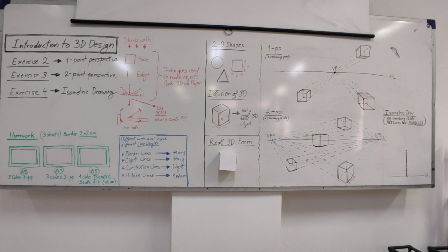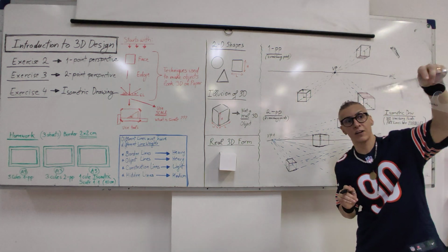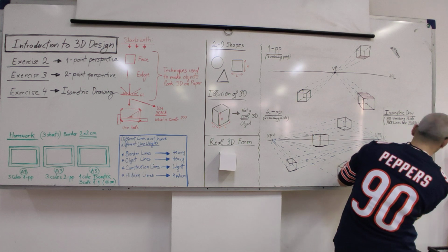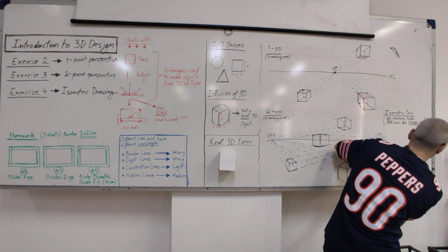Okay, great. Now we need to draw using our T-square and 30-degree ruler. So imagine the T-square is here. We need to draw a 30-degree line that goes from this point here. Then we flip the triangle and do the same from the other side.